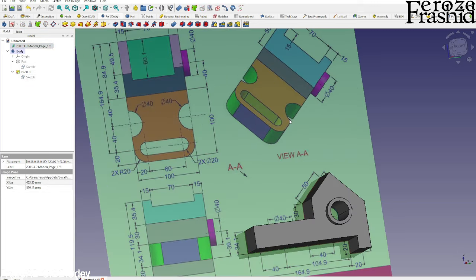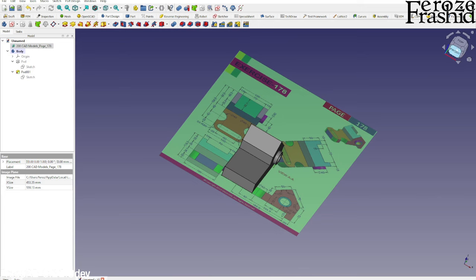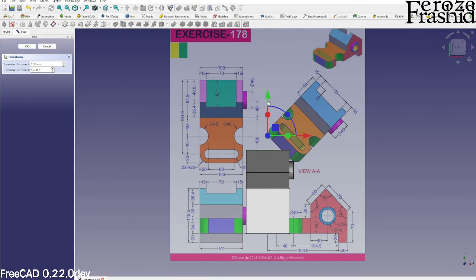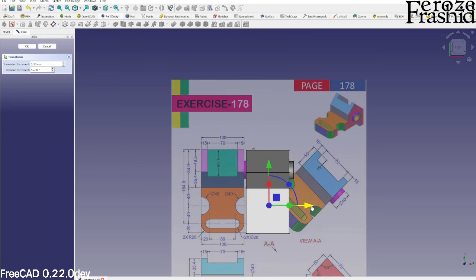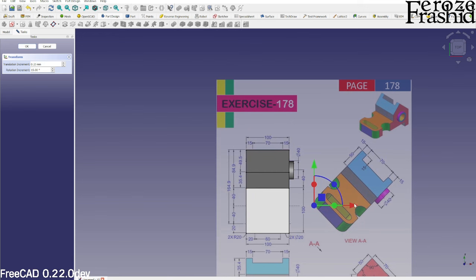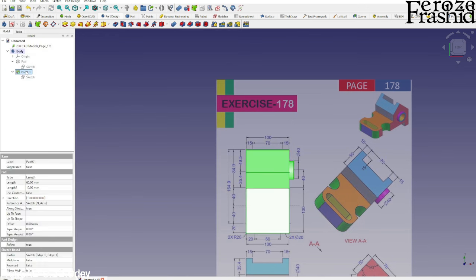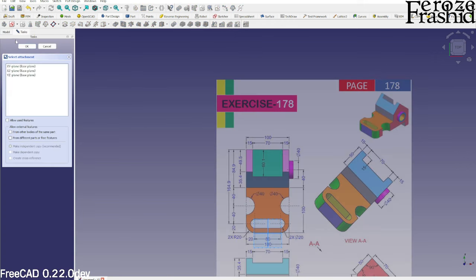Now the rest of it is pretty simple. I want to build this indentation and then cutouts in here. So I'm going to go ahead and place it on the XY plane and relocate the image to match with our already built object there. All right, and then it will be a sketch on the XY plane. I'm going to go ahead and hide this pad and draw a sketch on the XY plane.